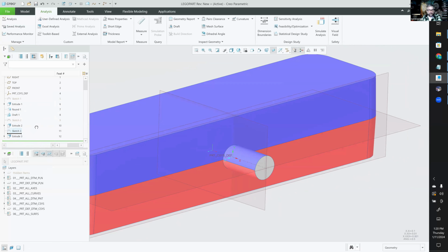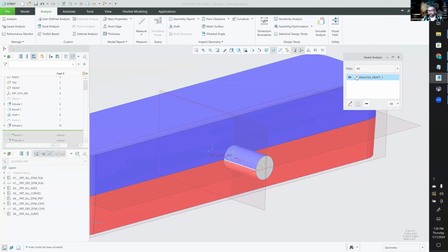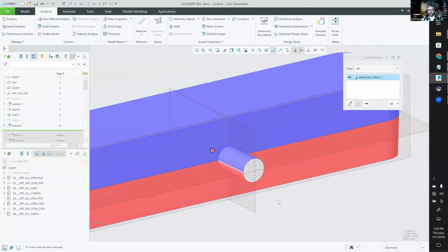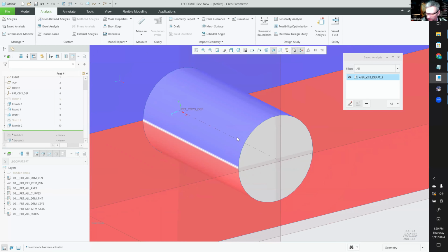All right, so I'm going to go to insert now before the eyelet part, and look how you've got this sort of gradient occurring here. So if there's texture on this part, which most parts have some bit of texture on them, it's going to get what we call a scrape mark in the tool as it starts to wear the texture off the tool, and we get kind of a shiny spot, which is the sign of an amateur engineer doing plastic parts.